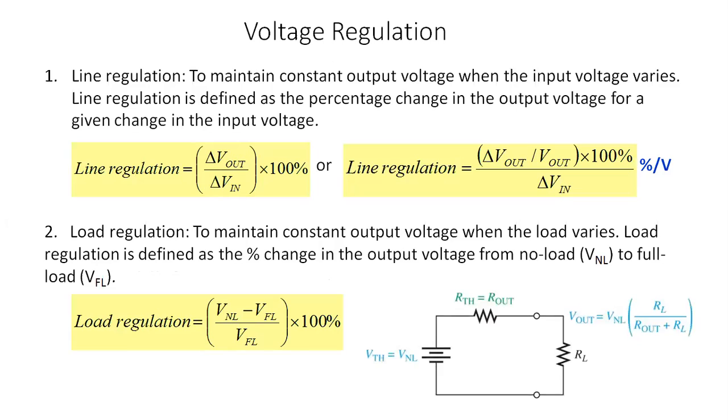So here, voltage regulation, already we have seen about the voltage regulation. What we are saying, by using a DC to DC converter, we are supposed to make the output voltage constant irrespective of changes in the input voltage or changes in the load or changes in the temperature. In that way, we are saying we will get different parameters in the voltage regulation. These are nothing but line regulation, load regulation, and temperature stability.